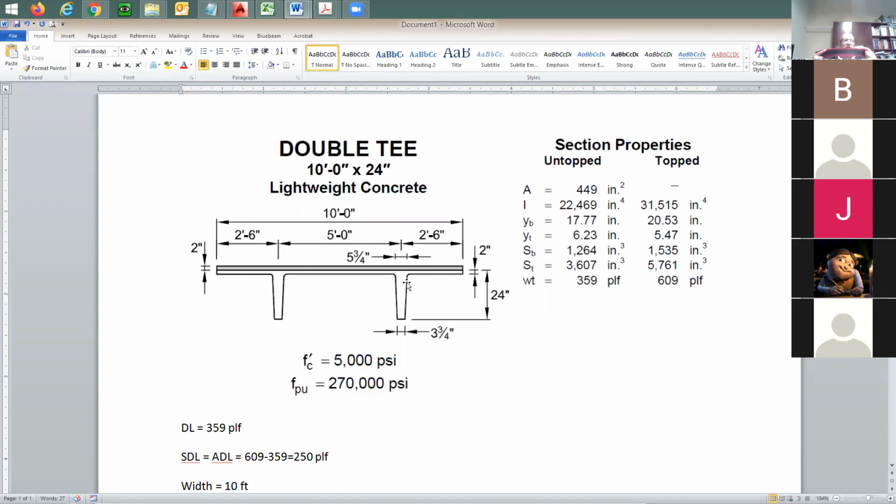You say, no way, because the stress is already going to be in the double T only, not on the topping. The top is not going to see any of this compression force. The topping is going to see the additional moment effect on the stresses. It will never see the axial compression on the double T. It is already there. It is inside the double T itself.